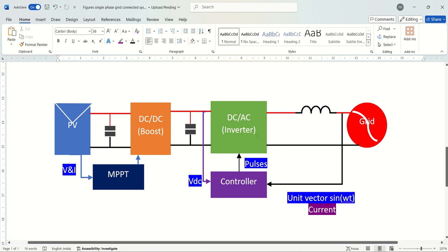Next, this DC link is DC power, and we try to convert this DC power into AC by using an inverter. So here, what do we have to maintain? One is 400 volts, which we have maintained. At the same time, whatever power is generated has to synchronize with the grid, because this is not a standalone process.